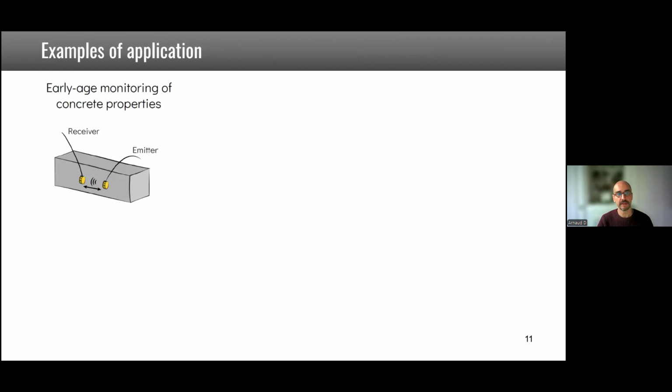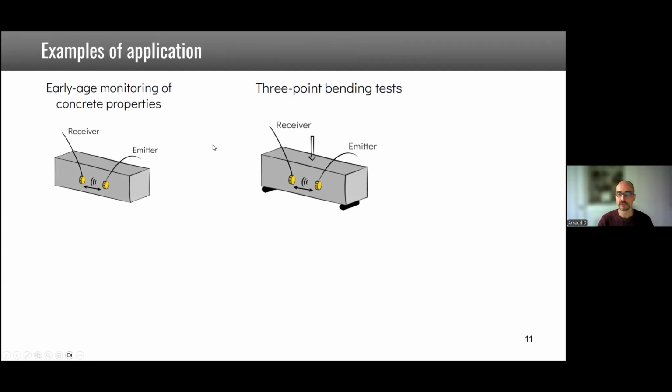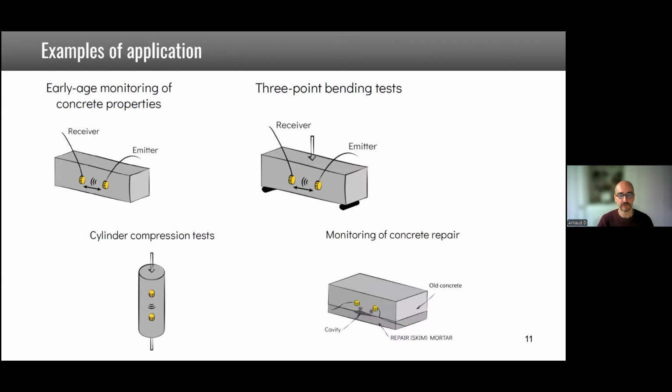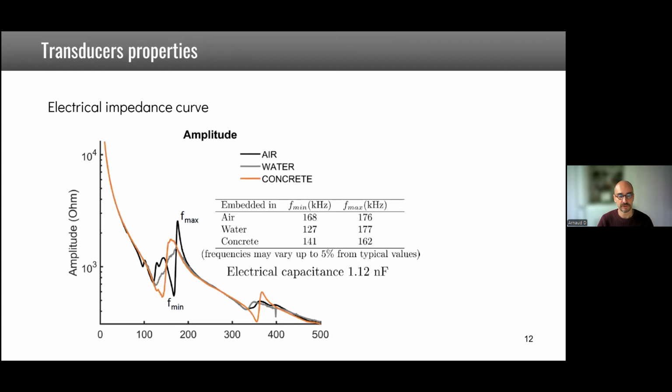And we have applied them in early age monitoring, so following the setting of the concrete, also in 3-point bending tests, for example, on small or larger beams, reinforced or non-reinforced. We did a cylinder compression test also with them, and that's what I will talk about. Also monitoring of concrete repair in some tunnels in Brussels.